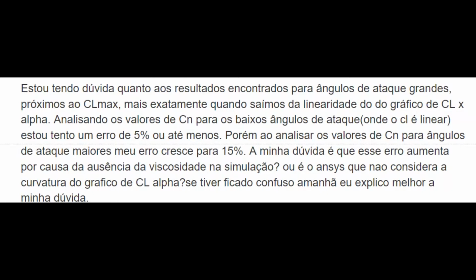Either you change velocity, which is difficult because you can come to compressible flow, and we don't want to calculate compressible flow. The other possibility is to change the size of the body, the chord value. So it's quite safe, and just by adapting the chord, I can calculate the same Reynolds number as my experimental data.